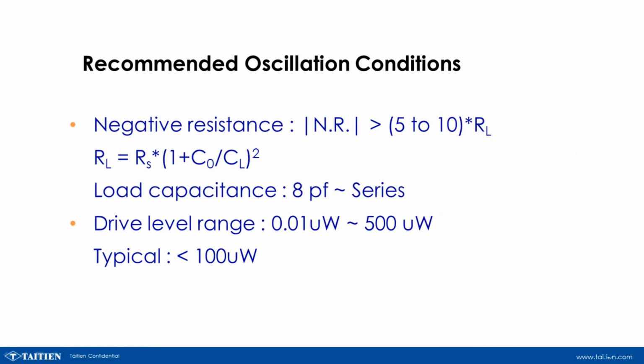The drive level of the crystal and the negative impedance of the oscillation circuit may affect the crystal's lifespan and oscillation stability. Common oscillation failures are caused by these factors. The suggested range of each parameter is provided in this video for your reference.